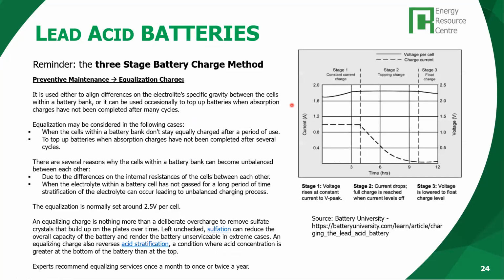To perform the equalization, the microgrid manager switches to the grid, since it has a much more stable behavior than the photovoltaic installation. In this way, it contributes to considerably extending the useful life of the batteries. It's important for the maintenance of the batteries.